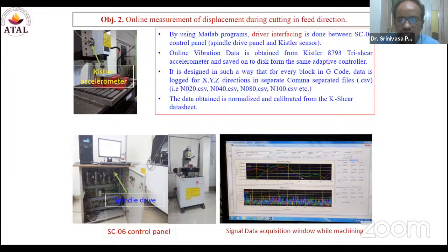If you ignore this amount of vibration, the machine will definitely run, but the life of the cutting tool will deteriorate, and this reduction in tool life, change in tool wear value and sharpness value is going to be reflected on the workpiece surface in the form of surface roughness.